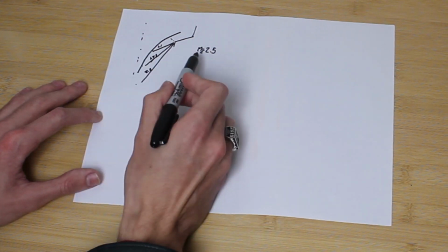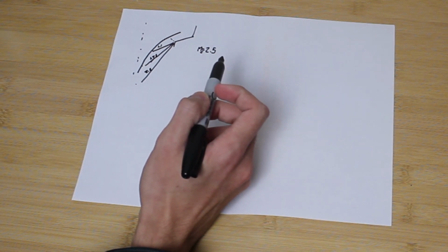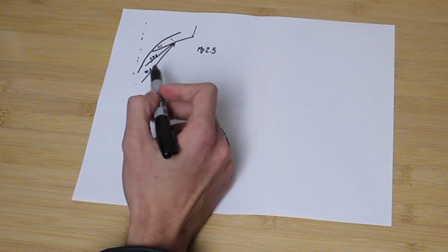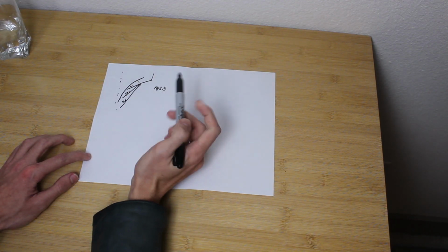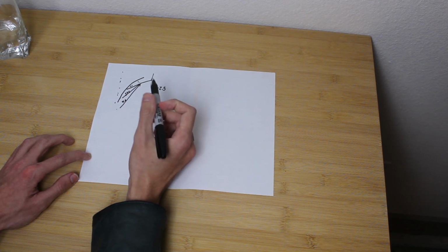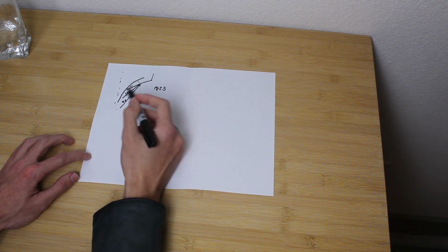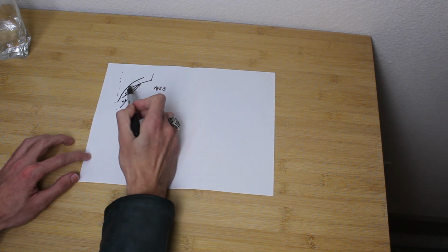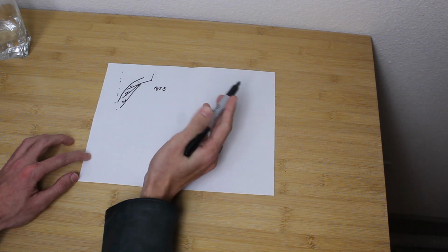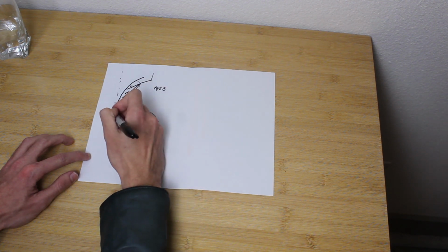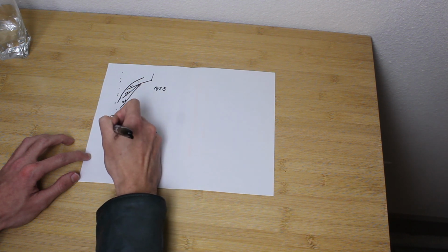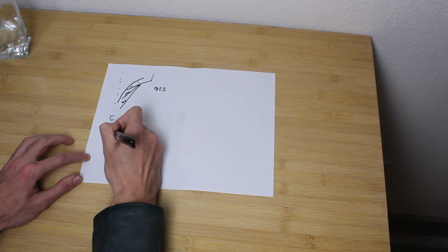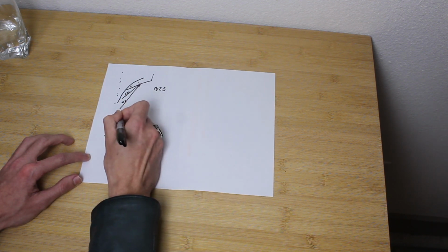So now that we've got this setup, we need to talk about how we solve for the properties of these expansion lines. Alright, so we've got these three Mach lines here, and we need to solve for the Prandtl-Meyer angle at each of these lines, which we can do because we have the Mach number, which we've chosen a priori, right? So we've plugged in the Mach numbers, and now we're going to solve for the Prandtl-Meyer angles. So we've got the Prandtl-Meyer angle for Mach 1.1, the Prandtl-Meyer angle for 1.75, and then the Prandtl-Meyer angle for 2.5. And these equal